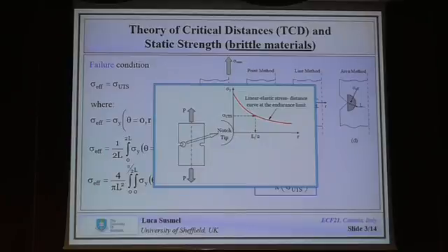So a trick we use to determine the critical distance is based on the point method argument. If we have a specimen containing a known geometrical feature, we can plot the corresponding stress-distance curve in the incipient failure condition, and L divided by 2 gives the stress, which is in turn equal to the material UTS.